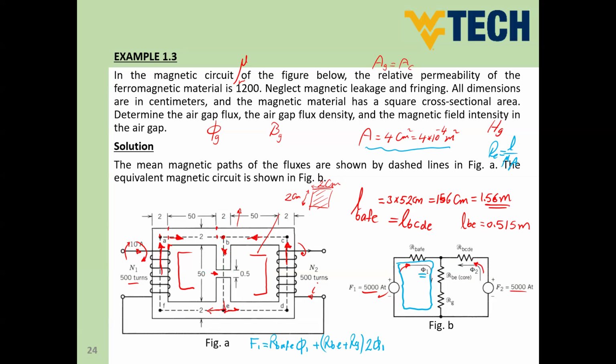of the applications, but for sure the kilowatt hour meter magnetic core is very small compared to this huge magnetic core. This is 1.5 meters, so this is a huge core. We may have some huge cores like that without an air gap, like in transformers. For power transformers, the core can be huge and the current can be relatively high, and also the flux can be relatively high. With this dimension of magnetic cores for a transformer, the amount of power may reach maybe half megavolt ampere. So this is going to be a huge amount of power, not only for a 10 amp. This would be maybe hundreds of amperes flowing in such a transformer with this dimension. Okay, nice.